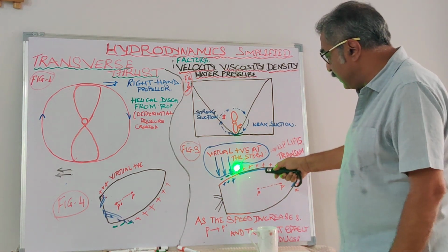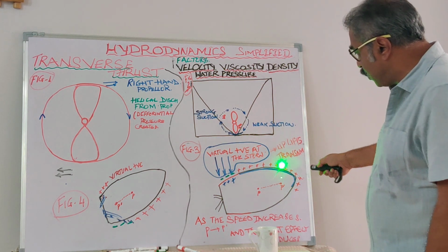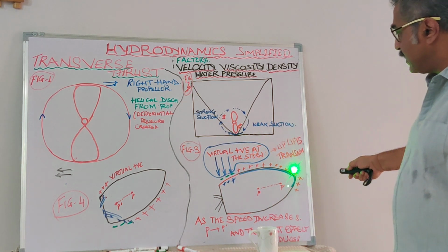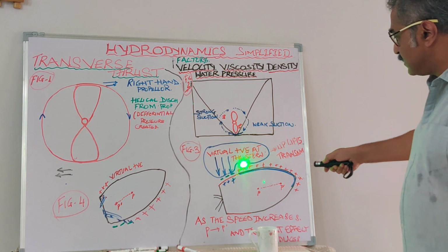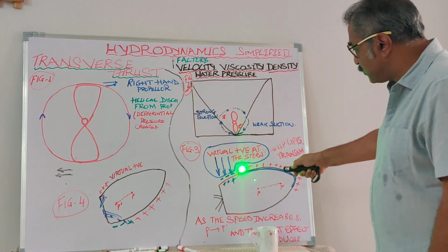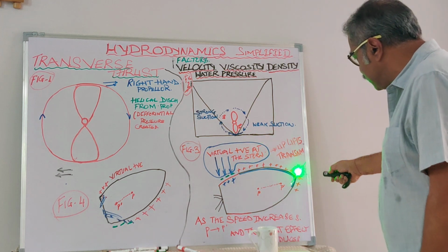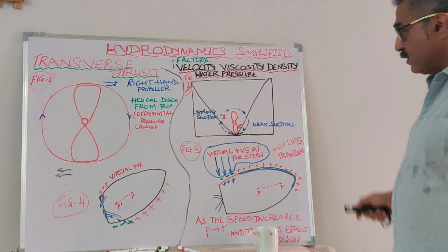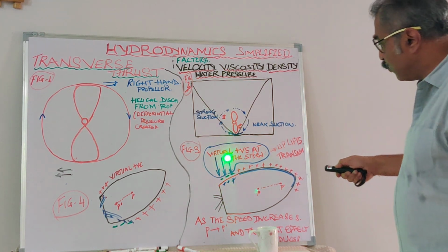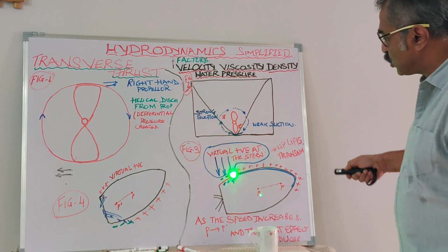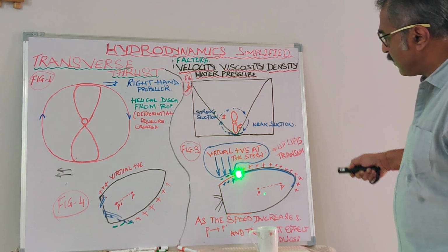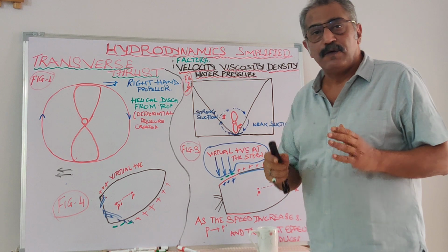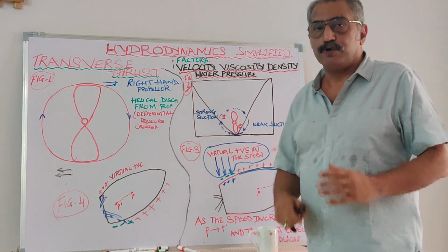But till such time the speed is less, the positive forces are on the port side, and the vessel will keep on experiencing them while the transverse thrust effect is predominant. The moment the speed is increased, all these positive forces will shift and lie somewhere here. During the same time, as I said earlier, the virtual vacuum or virtual push at the transom, at the stern, will be created, which will enhance the effect of transverse thrust for a vessel to turn to port on a head motion.